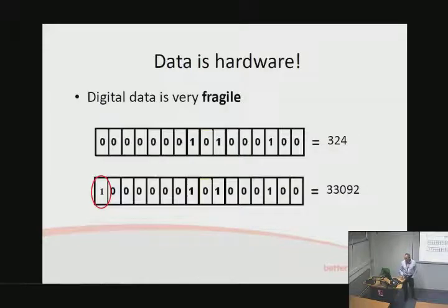And let's look at that, because the key point here is, as we showed how analog information degrades gracefully, if we set a single bit the wrong way because a piece of noise has corrupted it across the threshold, the information degrades very, very quickly to completely random numbers. It doesn't just degrade by small amounts. And so for a lot of systems that can be disastrous.